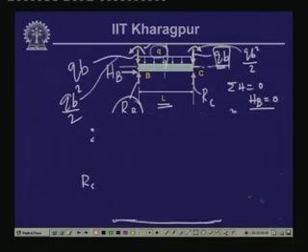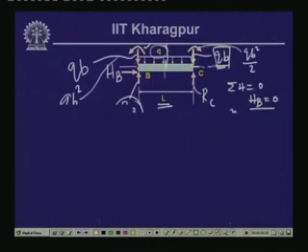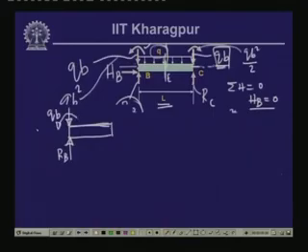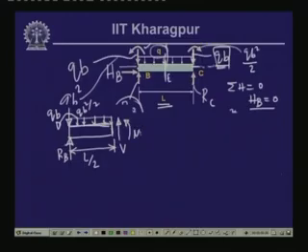Now, if we calculate the value of the bending moment at E, taking the free body part of this particular end, say the left end of the beam, here we have the vertical reactive force which is RB, and HB being 0 we are omitting that. Here we have the vertical force which is QB, and we have an anticlockwise moment which is QB square by 2, and we have over this particular part distributed load of intensity Q, and this being the mid span, this length is equal to L by 2. On this cut there will be the stress resultant which is the positive shear V, and the bending moment M which is anticlockwise.